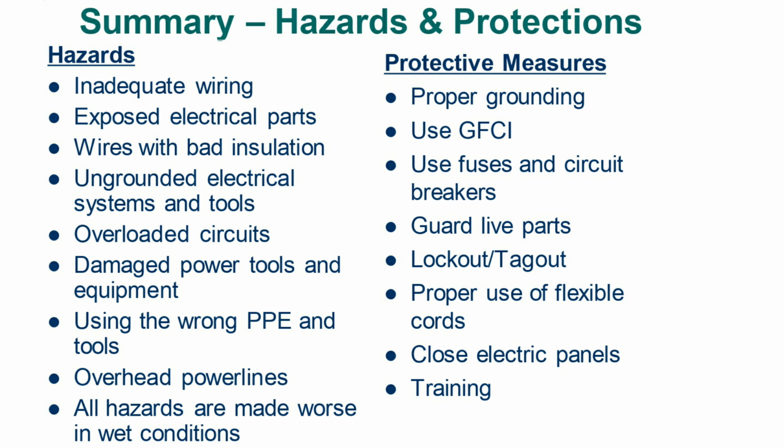Protective measures: proper grounding, use GFCI, use fuses and circuit breakers, guard live parts, lockout and tagout, proper use of flexible cords, close electric panels, training.